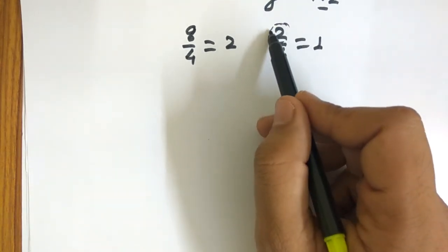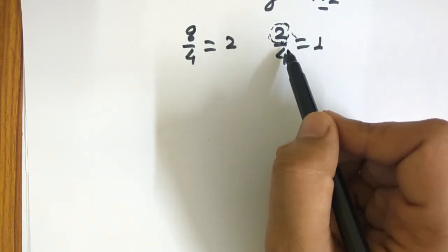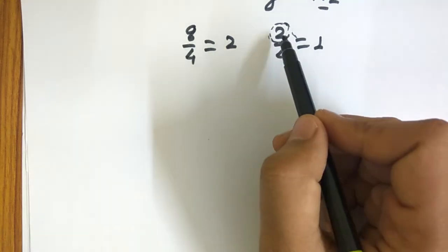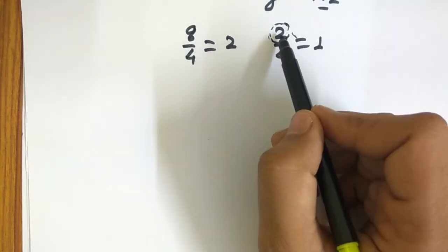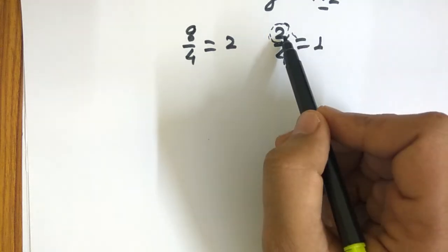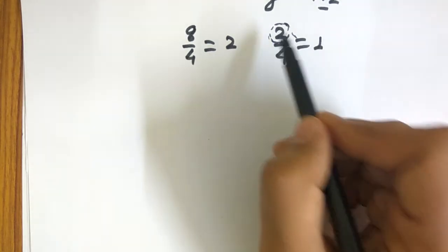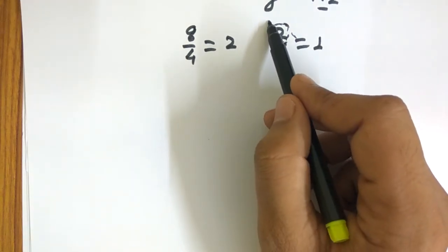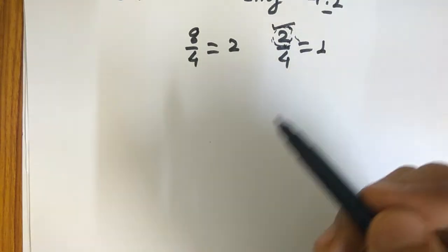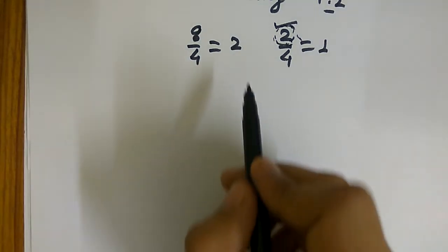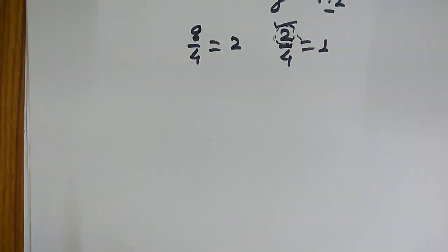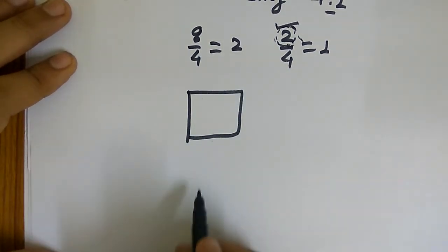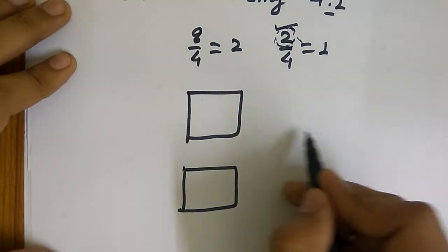Here we have only 2, so for the mux used for the MSB, we will use only 2 inputs of that one. This is the meaning if any mux is not completely divisible when we are dividing. So here we will use 3 mux. So this is 1, this is 2, and this is 3.